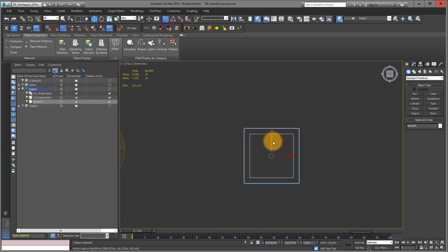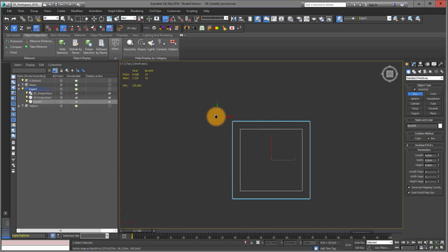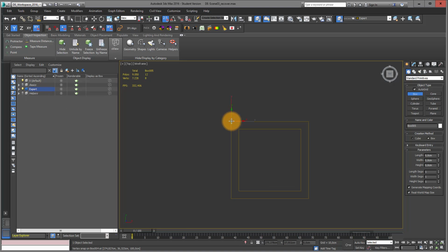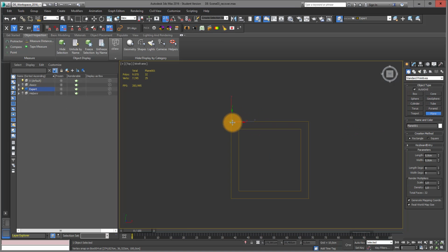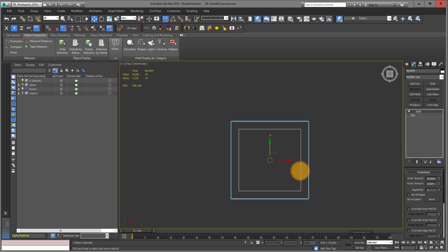So if I just measure the dimensions of this, and I just do it with a simple box. I just go inside, I have my vertex snap toggle on. I just click first time and also here, and you just can see that I do it again, go into a box. By the way, I can also use plane, it's probably easier to see. So I just draw a plane. You can see this is 10 by 10 centimeters. That's also a really easy way of how to measure things. I just delete it. So this is 10 centimeters. This is obvious. This is what I actually expected.